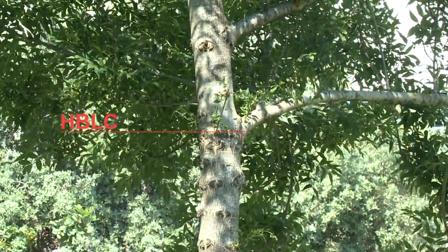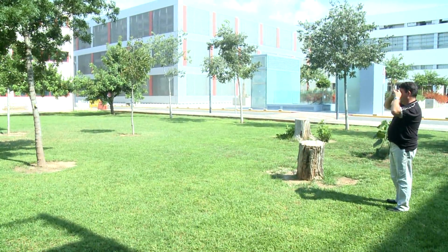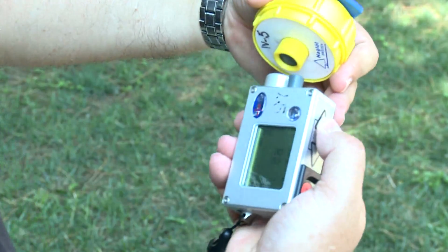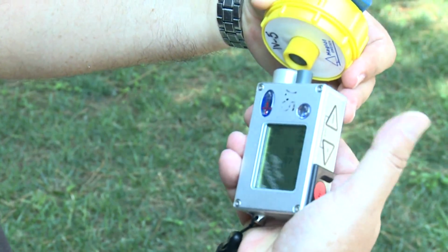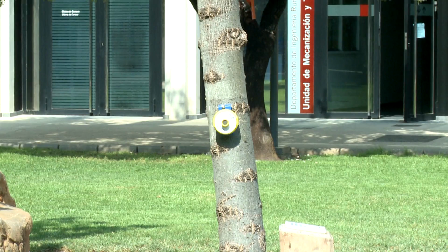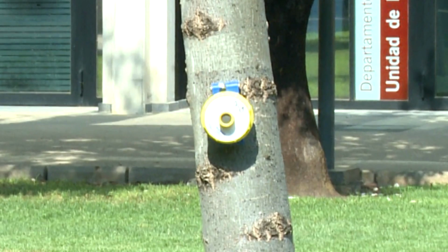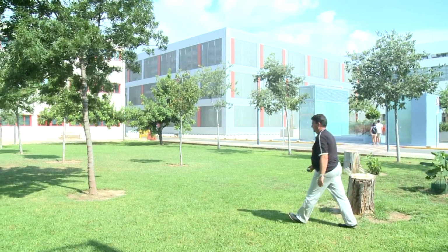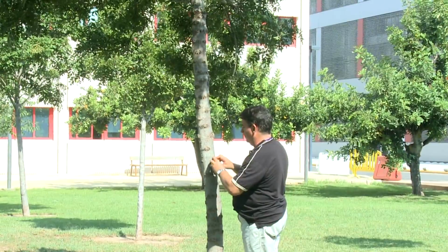For height measurements, we may use several direct and indirect ways and devices. The instrument especially designed to measure the tree height is called a hypsometer or height measurer. We may use an ultrasonic hypsometer that can provide range distance and several heights, just with the use of the transponder that will send the ultrasonic wave back and set the reference position of the observer. To measure the tree height, we place the transponder over the tree bark at the breast height section.